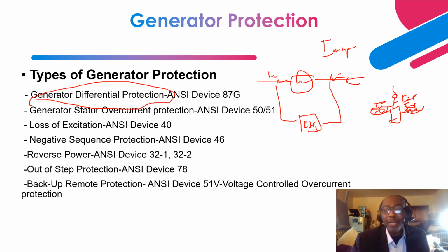The minimum operating point is selected based on a lot of factors, right? And that is basically put into place. That is based on CT characteristics, right? Where a percentage is factored into that to decide on the minimum operating point of the differential relay. Next is our steady overcurrent, right?